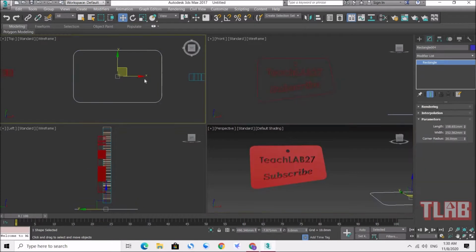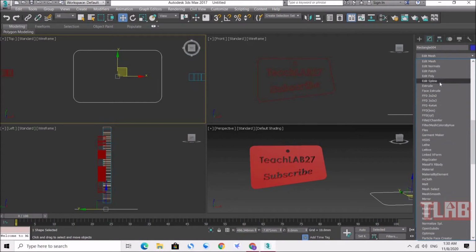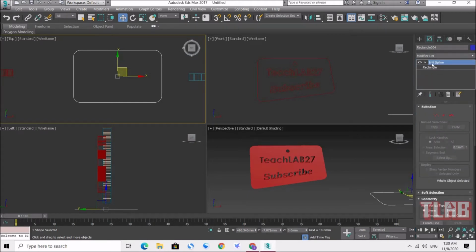You still remember last time in lesson 4 I mentioned that if you want to edit a spline object, you need to use Edit Spline. That means you want to edit in more detail. So you select the model, then go to the modify list and click Edit Spline. After clicking, you can see the selection, and inside there is a vertex function. Just click it, select these two, and move them up a bit. And this one also. Just move it.